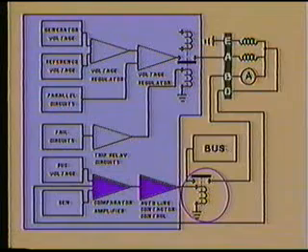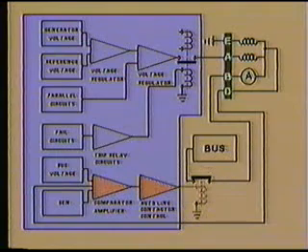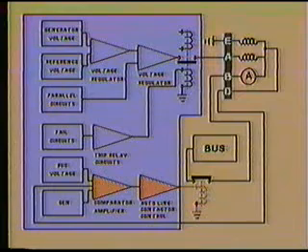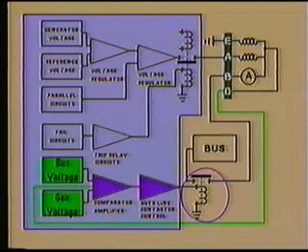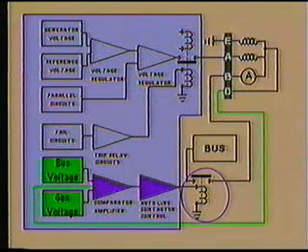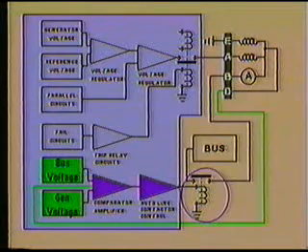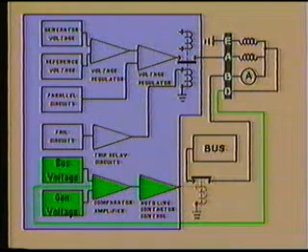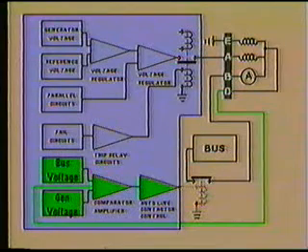The contactor amplifier receives its input from a comparator amplifier. When the comparator amplifier has an output, the auto line contactor amplifier will have an output, and thus the relay will close. For the comparator amplifier to have an output, it must sense that the bus voltage, generator voltage, and voltage present within the interpole windings in the generator are at their proper levels and polarities. When each of these signals is correct, the comparator amplifier will have an output, which will cause the auto line contactor control to close the main contactor relay.